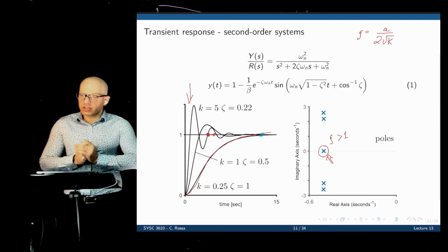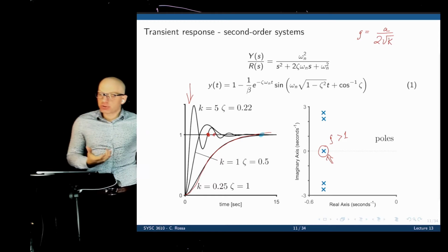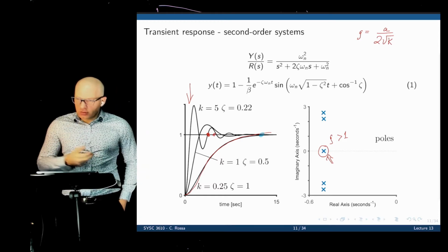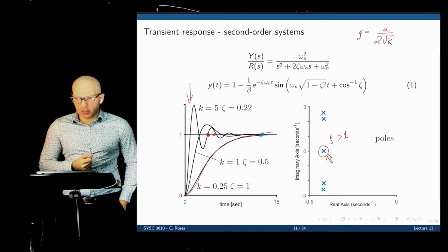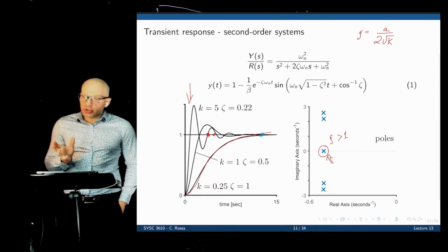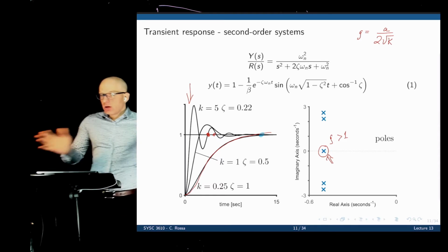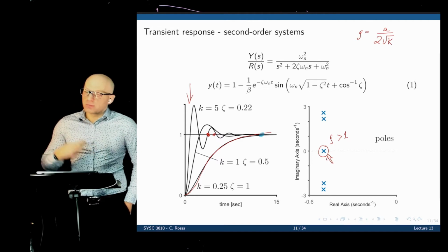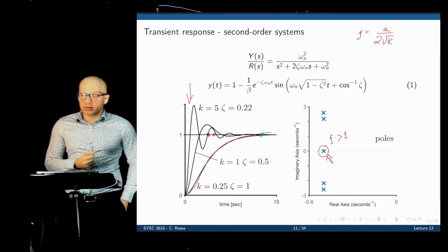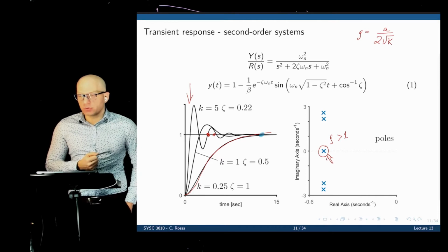And as designers, now we need to come up with metrics to define the overshoot and to define how long the system takes to settle. So for a second order system, now we have all this range to work with. We have an exponential and an exponentially decaying sinusoidal waveform.